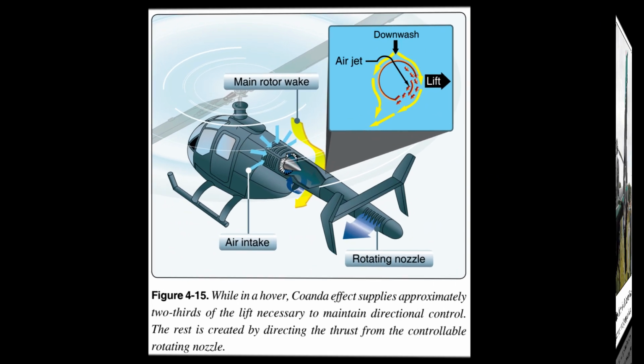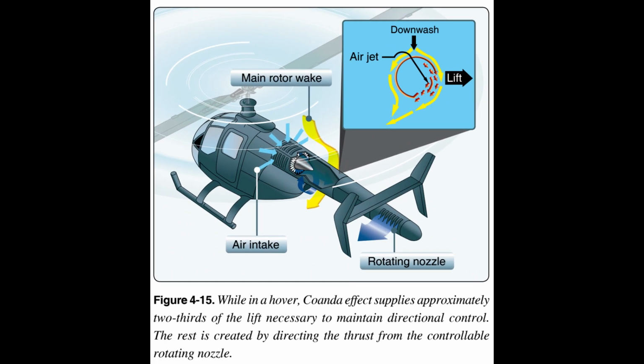NOTAR. Using the natural characteristics of helicopter aerodynamics, the NOTAR anti-torque system provides safe, quiet, responsive, foreign object damage (FOD) resistant directional control. The enclosed variable pitch composite blade fan produces a low pressure, high volume of ambient air to pressurize the composite tail boom. The air is expelled through two slots which run the length of the tail boom on the right side, causing a boundary layer control called the Coanda effect.